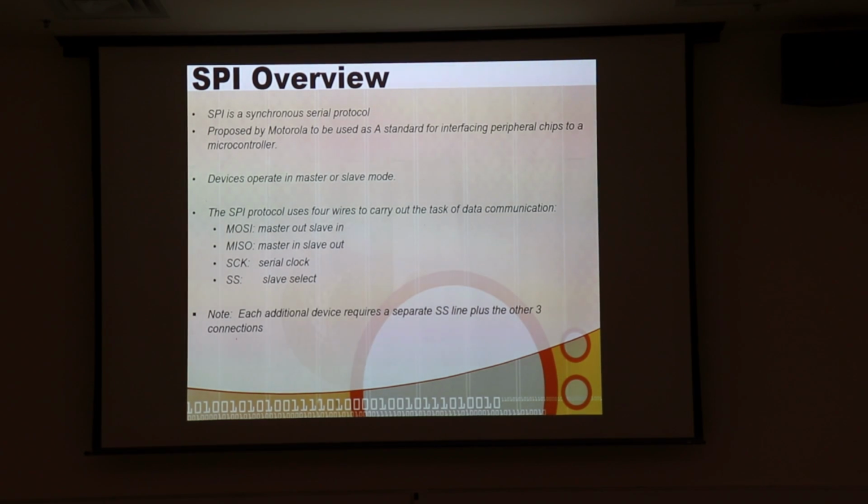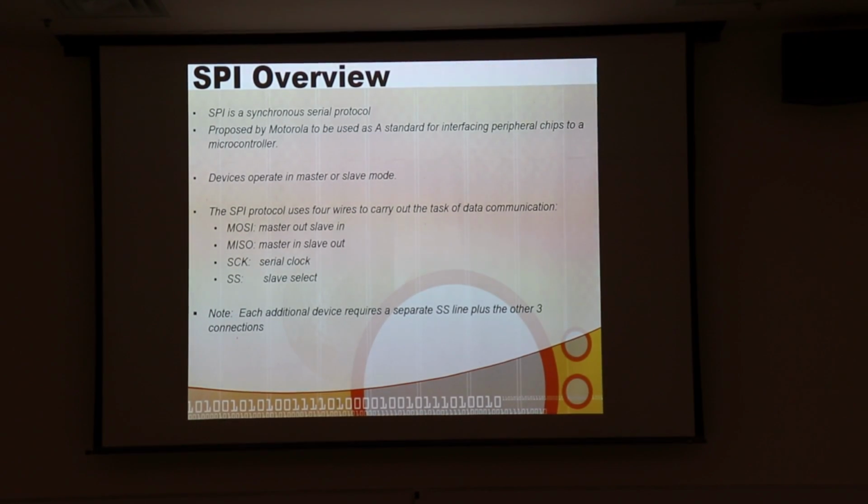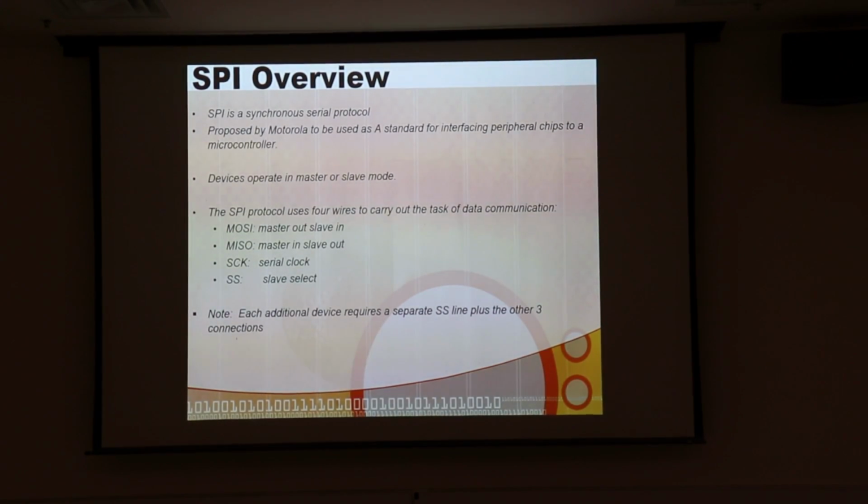Normally you have to send data to the slave, and then the slave decides what data to send to you, and then you do another one. So most of the time, when you talk to the slave, either the slave or the master is sending dummy data going one way, and real data is going the opposite way. So typically, you're not taking advantage of the full duplex feature. But you could, in theory, do that. It's just that it's rare that it works out that it's possible.